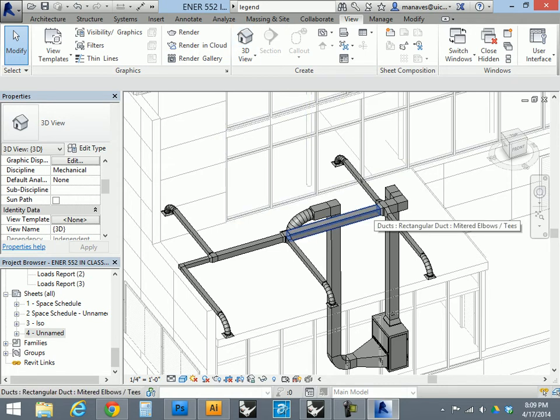So what we're going to do now is create a new system. So you've done your spaces, and then you set up the zones. We dropped zones, so you zoned everything. We applied spaces to the zones. So now we have to set up a system for a specific zone.